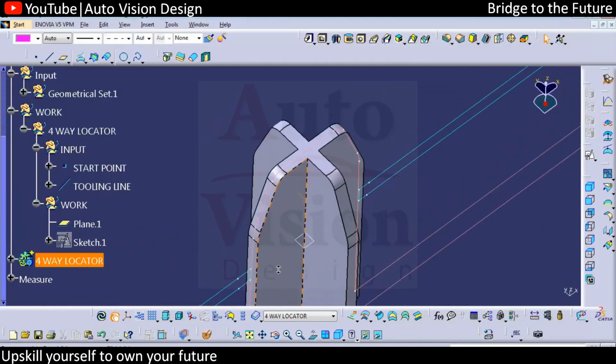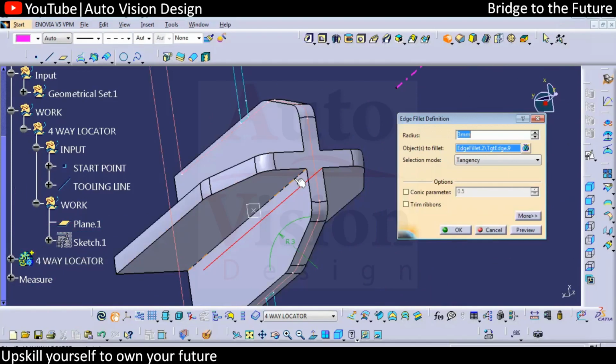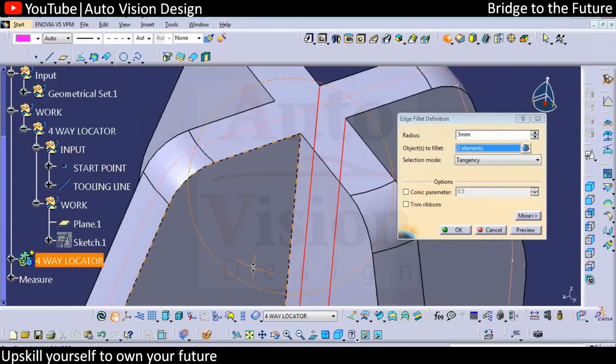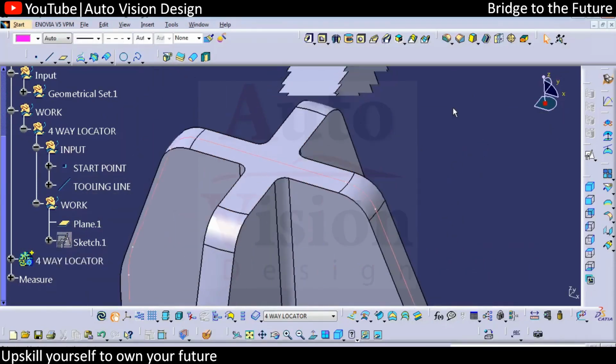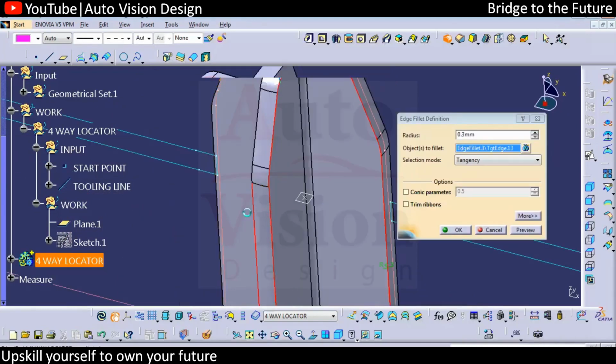Again, if we want, we're going to add the 0.3 fillet to the locator. Okay, because there will be the tooling fillet by default, for that reason we're going to add this 0.3. Okay, then we're going to run this fillet from the periphery.